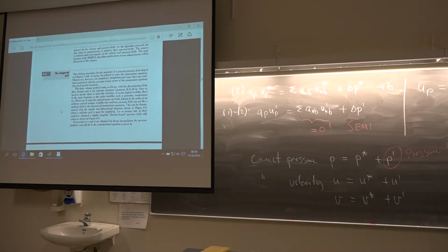So he's just an explicit expression, so no problem to finding him. But now with this equation, you see we can rewrite this velocity correction, which is still unknown, in terms of the pressure. So what we get here will now be something like this: 1 over the coefficient, and then with something with this delta pressure correction like that.